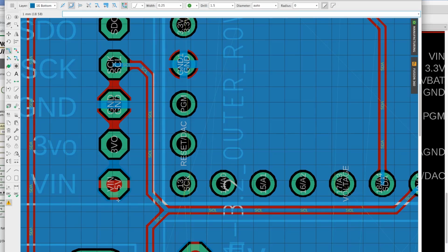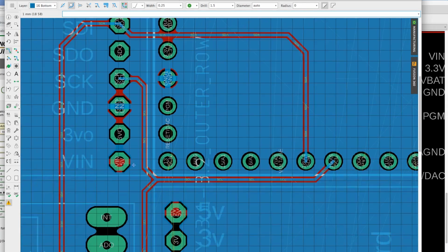And actually, you might be wondering, hey, how do you power these devices? Well, we don't even have to worry about that anymore, because if you look close, we have the 5-volt signal connected on the top plane and the ground signal connected on the bottom plane. And same thing for the IMU here, same thing for a lot of these devices.